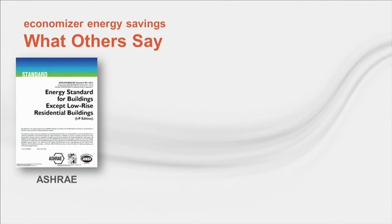Throughout the industry, most practitioners and organizations agree that economizers can be used to reduce HVAC energy usage. The requirements for economizer usage in 90.1 come from energy studies commissioned by the ASHRAE 90.1 committee. These studies have supported the usage of economizers in all but the most humid climate zones.